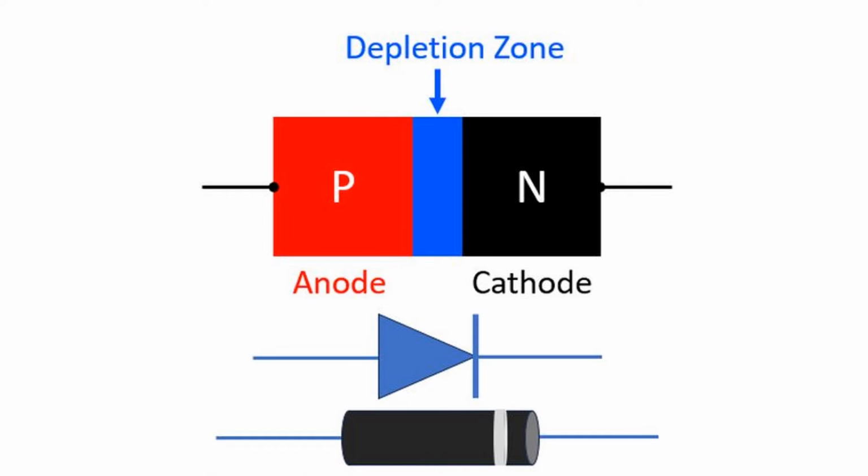For this crossing to occur, there should be at least 0.7 volt for silicon junctions and 0.3 volt for germanium junctions. At lower voltages, there is a depletion zone of carriers at the junction. This causes a current to flow across the PN junction when it is forward biased. In the reverse bias situation, no current flows across the PN junction. That is how a semiconductor diode functions as a rectifier, converting alternating current into pulsating direct current as it cuts off one half of the AC.